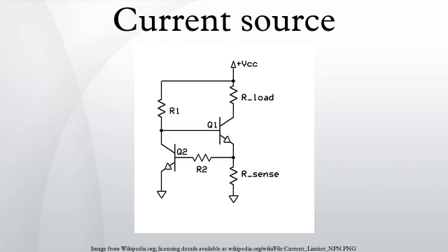Constant current source with thermal compensation. One limitation with the circuits in Figures 5 and 6 is that the thermal compensation is imperfect. In bipolar transistors, as the junction temperature increases the VBE drop decreases. In the two previous circuits, a decrease in VBE will cause an increase in voltage across the emitter resistor, which in turn will cause an increase in collector current drawn through the load. The end result is that the amount of constant current supplied is at least somewhat dependent on temperature.